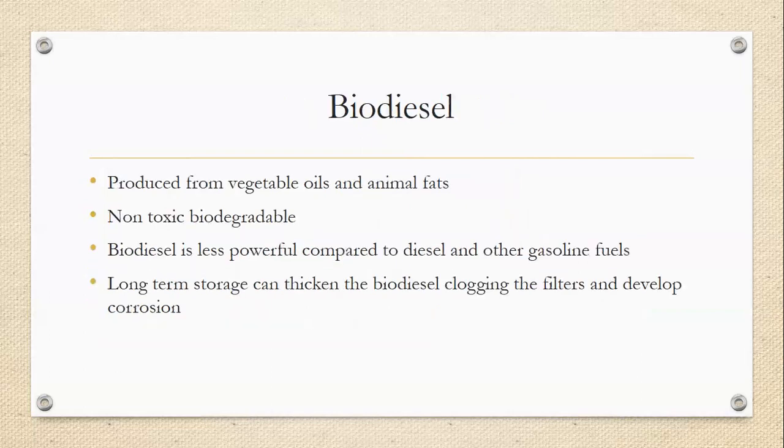Next alternative fuel is biodiesel. This biodiesel is produced from vegetable oils and animal fats. These are non-toxic, biodegradable, but biodiesel is less powerful compared to diesel and other gasoline fuels. One of the major problems of using biodiesel is that long-term storage of biodiesel can thicken and clog the filters and develop corrosion.